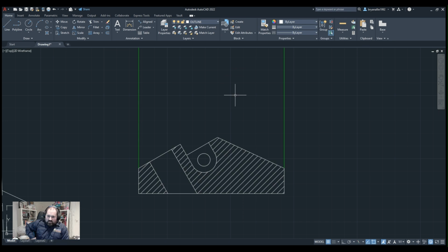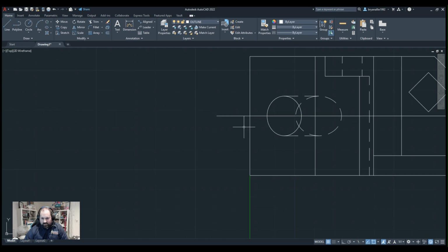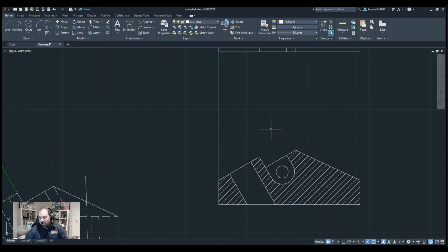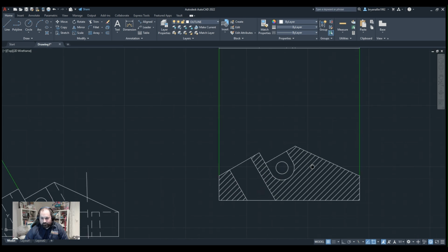It's like what you would have seen before when I sent you. Then when you do section views, you're just going to make sure that you have the view name on it. So this could be A to section view A. Then this has to be view A to A. Then the one I had earlier had the scale next to it.